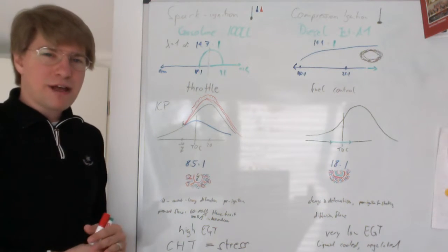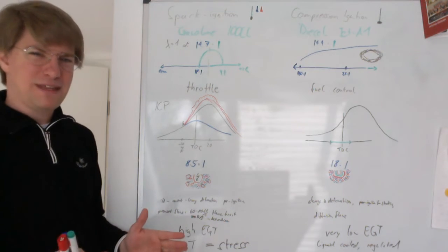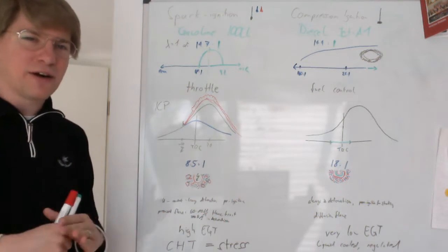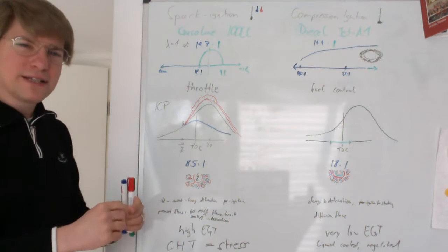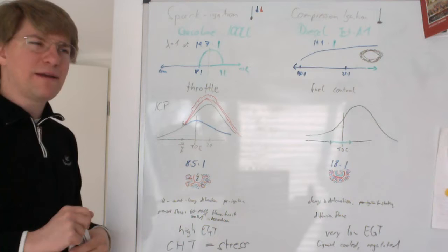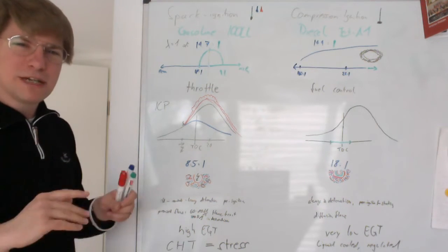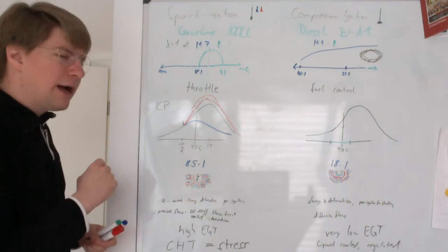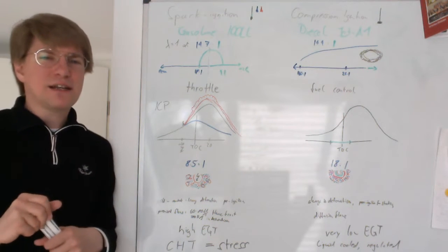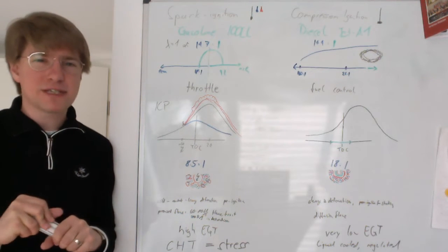So, as you can imagine, detonation is not a binary thing. It's not like the engine is either detonating or not. Those tiny pockets igniting ahead of the flame front can be very few and far in between. That's not really harmful. In fact, mild detonation is actually considered beneficial in some situations.